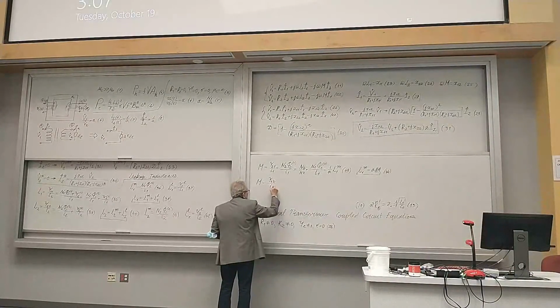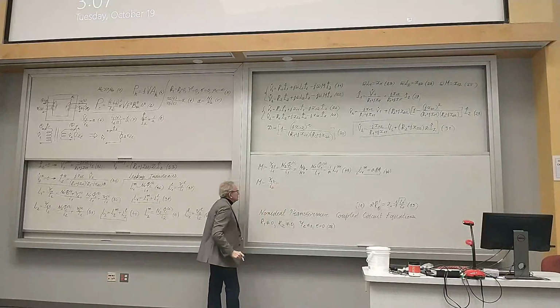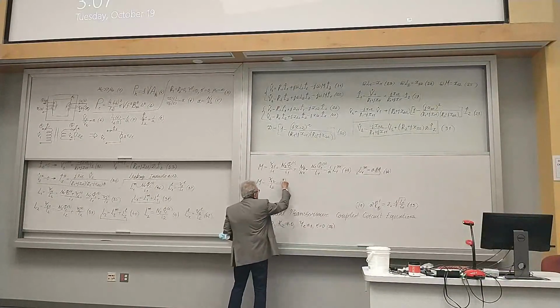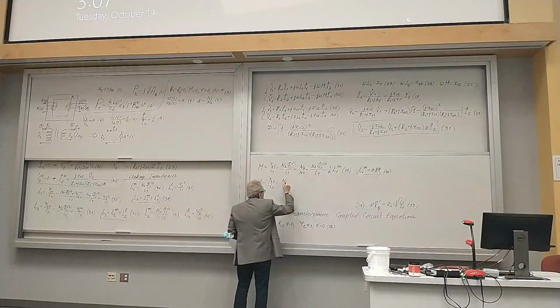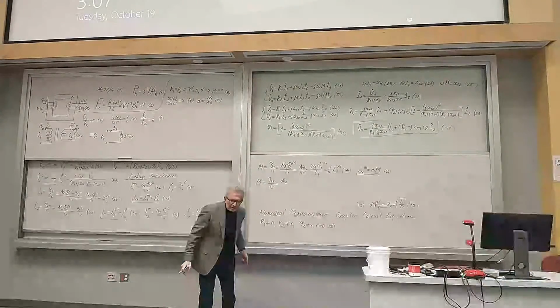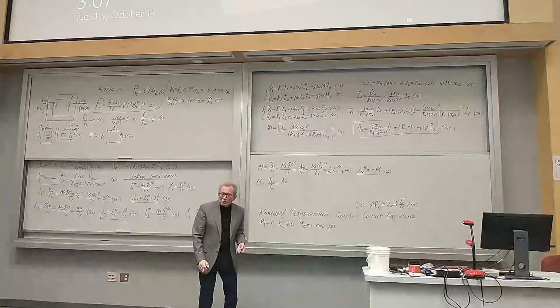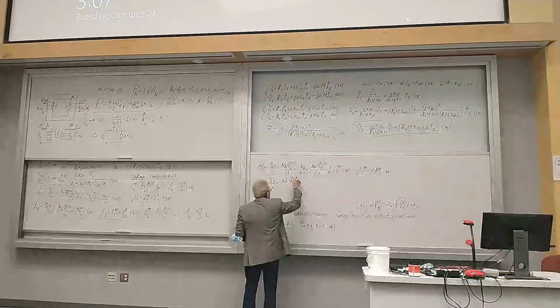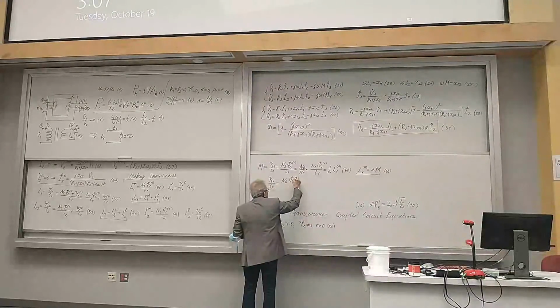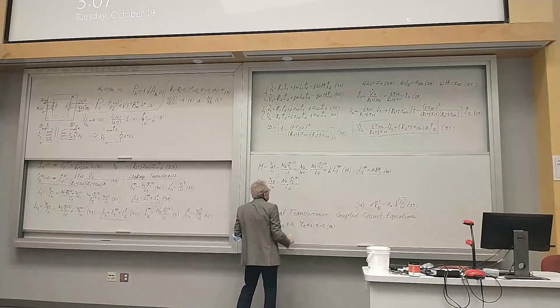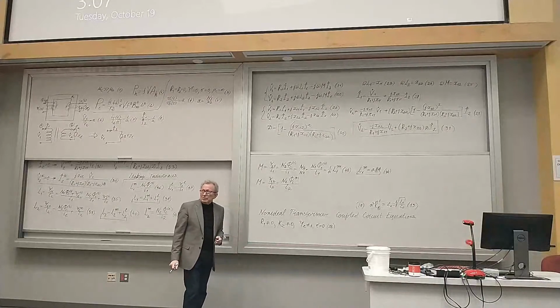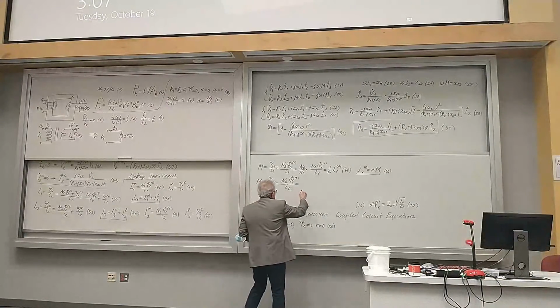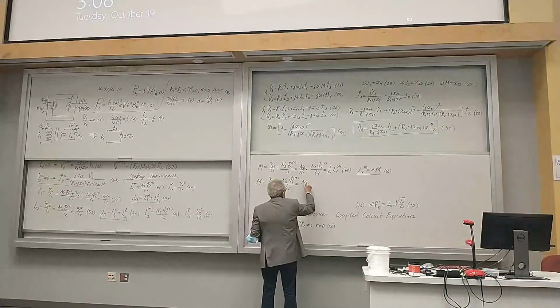secondary winding. And these flux linkages will be by and large due to the magnetic field lines which go through the ferromagnetic core. So it will be due to the core flux created by the secondary winding, which is excited, divided by I sub 2. And then I will do a similar trick. I divide and multiply by n sub 2.